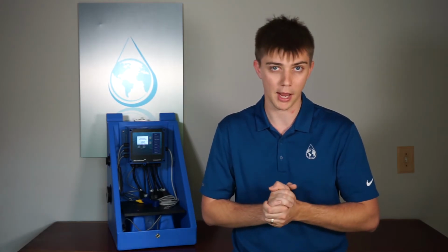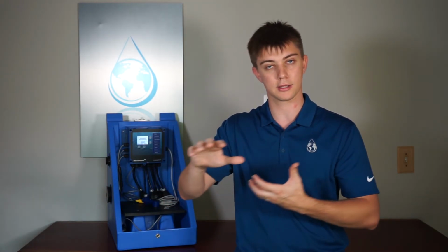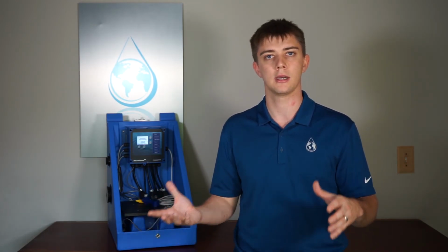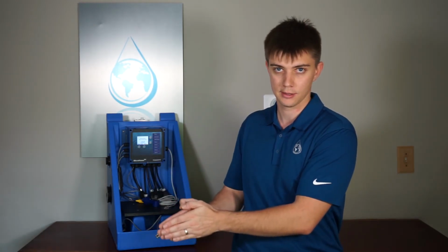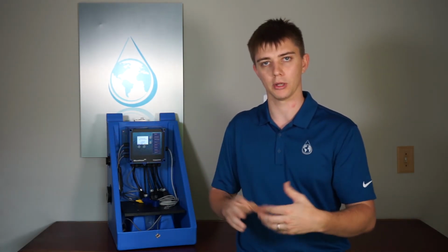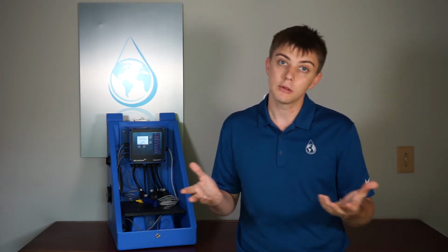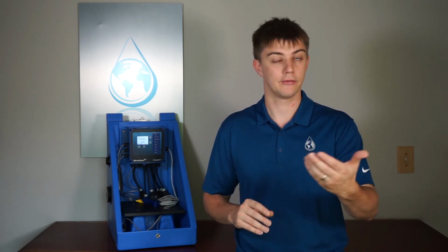You would pre-bleed a tower for a defined amount of time or until you hit a certain conductivity minimum. Then you would feed your oxidizing biocide, and then you would lock out bleed for a certain amount of time. Locking out bleed is going to allow that oxidizing or non-oxidizing biocide to circulate within your system to give you an effective kill on all the bacterial microbial life that may be in there. If you didn't do a bleed lockout, then there's a chance that you could feed product and then it goes straight to drain and you don't get an effective kill.